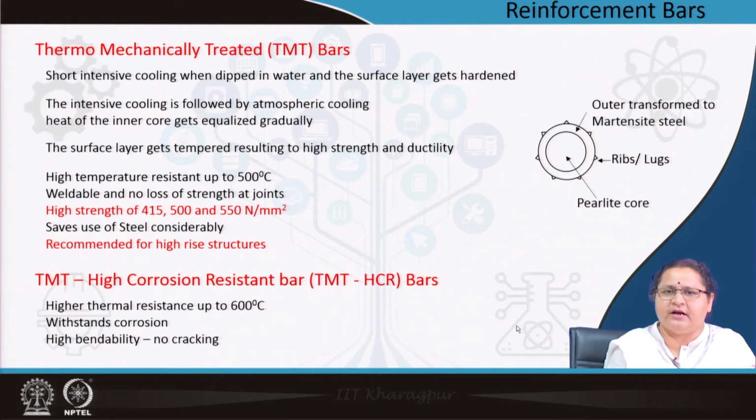Further, we have the thermomechanically treated bars, which have an outer layer of a different type of steel, inner of a different type of steel, achieved through heat treatment, having higher resistance to temperature, and TMT HCR bars having lesser chances of corrosion.